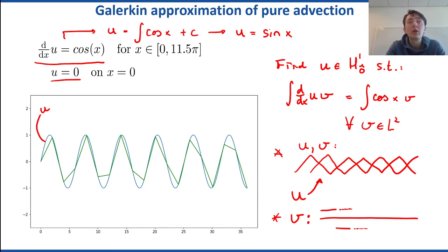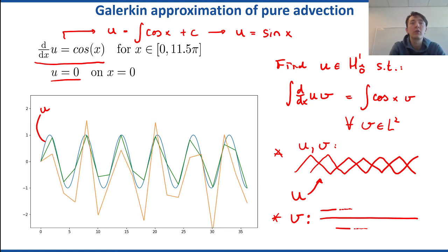And one particularly important thing to note here is that there are no overshoots and undershoots, right? So if our simulation is so sensitive to overshoots and undershoots because, well, for instance, we're dealing with a concentration, or another example would actually be a density, that you can't get negative densities, of course. So it's important that we satisfy certain maximum and minima requirements, and that's the case for this green line. Okay, and if I overlay those two results, then you clearly see that with the Petrov-Galerkin method, we get a much better result.